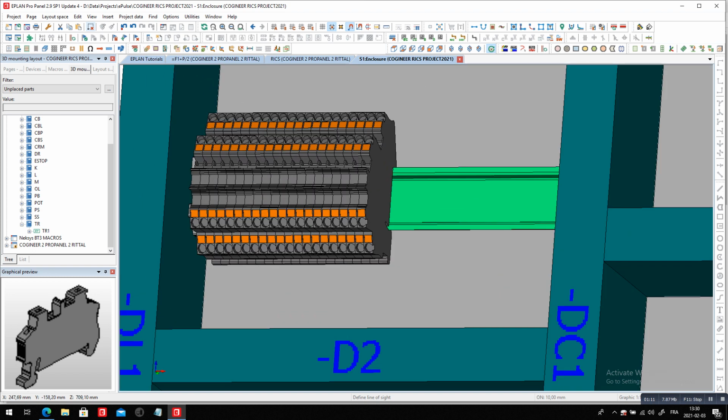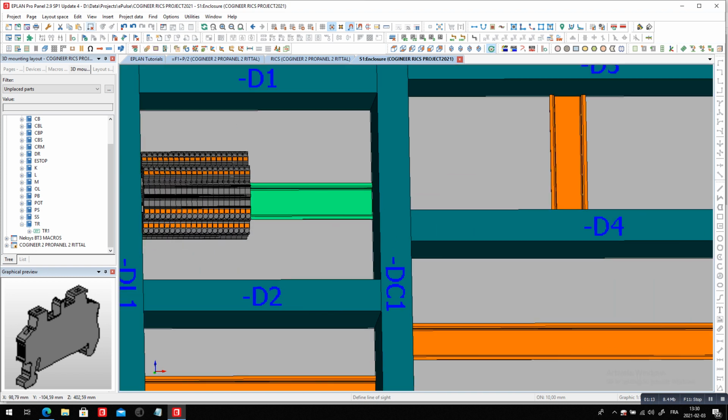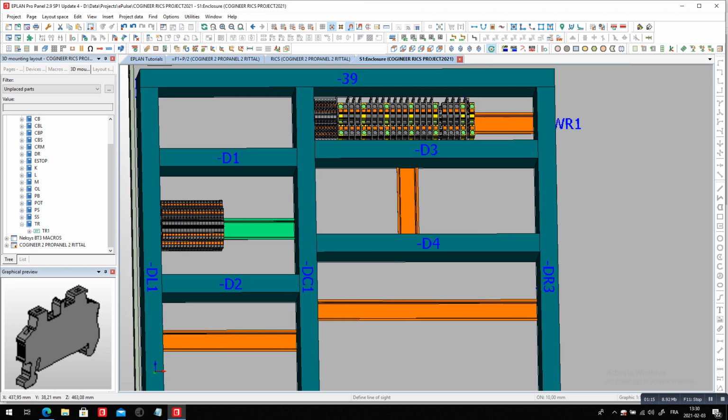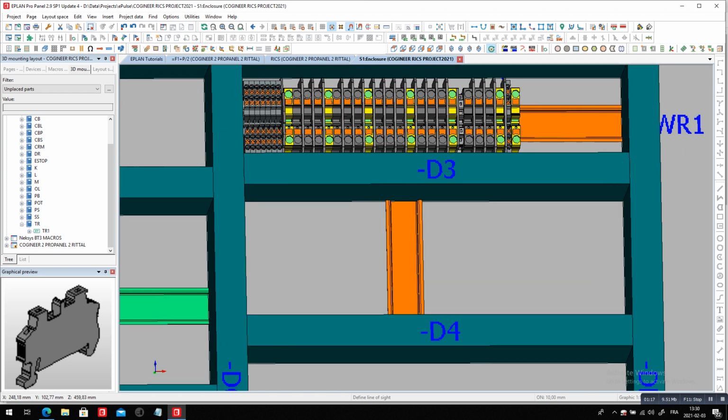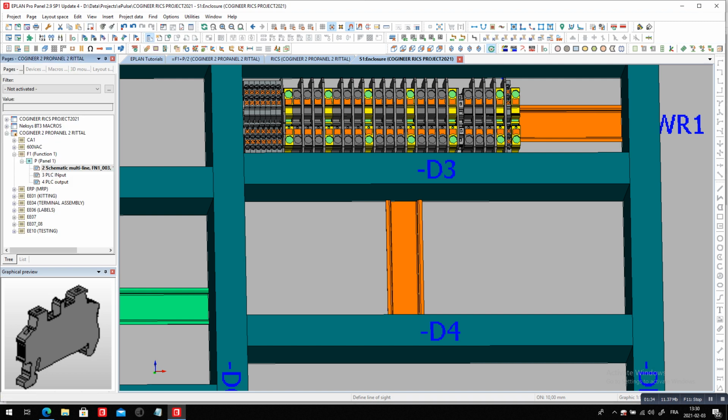And when we talk about terminals, we often talk about some special accessories. We talk about jumpers. We talk about different types of terminals, 4 connection, 2 connection, PE, when they're green-yellow like this. Some separating plates. In this case, it's not sorted in the right way. These should be at the end here. So there's a sorting aspect to this whole thing. But to start with, we have to go deeper and check out the schematics.